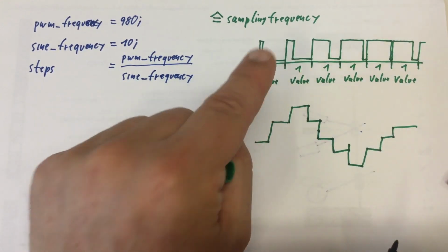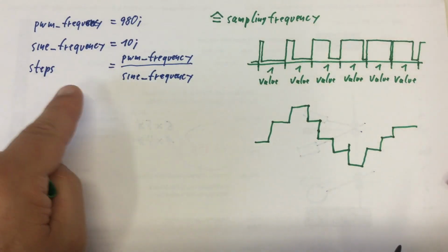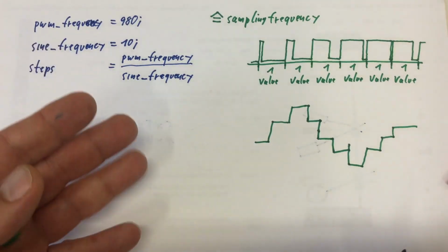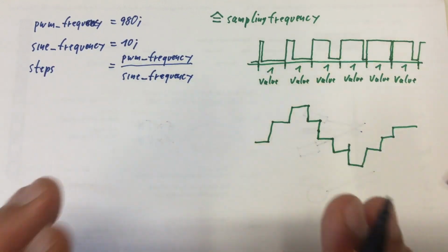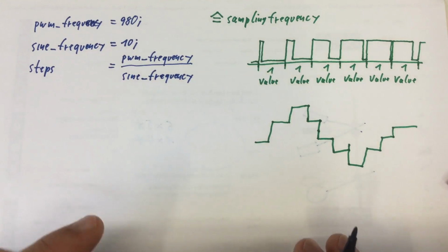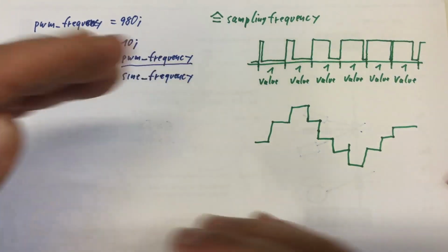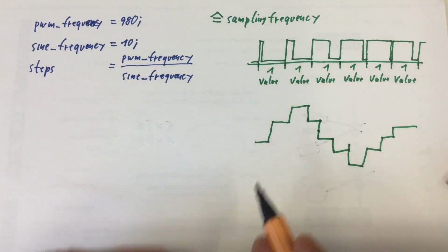This is really your sampling rate, and building bigger lookup tables for your sine or other function you output makes absolutely no sense. And of course, this is also a digital limitation for the bandwidth of the analog signals you can output.